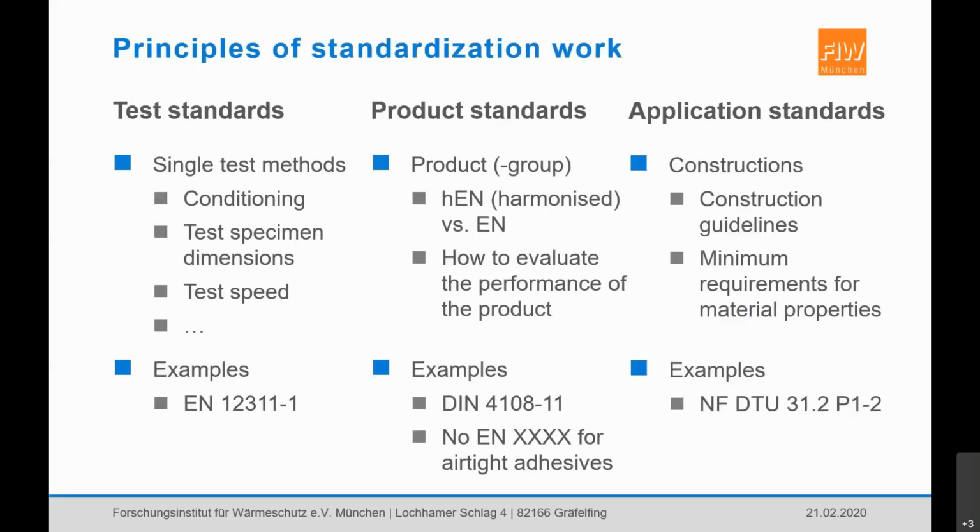So first, some principal information about standards, what type of standards are present. So starting with test standards, so these are standards for single test methods, typically with content about the conditioning of the materials, about the test specimen dimensions, test speed. So in general, all conditions that are relevant for a specific test scenario.